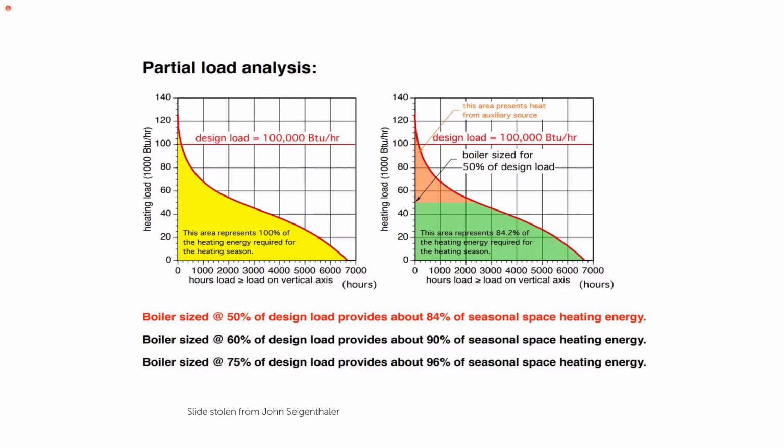If you have a design temperature of -11, maybe there's 100 hours annually where you're actually at that design temperature. Probably a lot less. And as we start to look at heat pump equipment as the direction that a lot of buildings are heading in, we have to be careful about sizing and specifying equipment with that factor in mind.